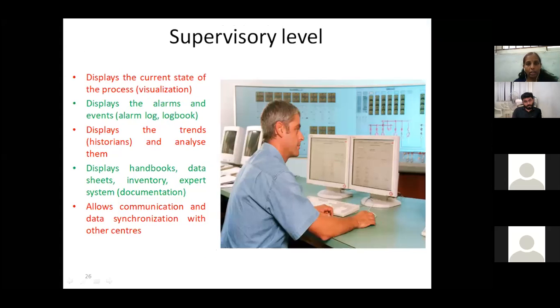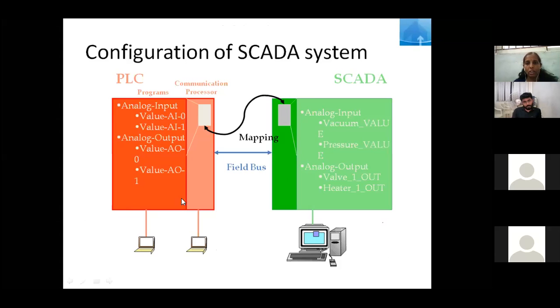So this is how a PLC can be communicated through a SCADA. All the IOs are communicated directly through the field bus. There is a server called the open access server, the OPC data server, through which data can be communicated. A separate software is used for this programming. For example, Allen Bradley and Rockwell Automation give RSLogix or Studio 5000 based programming software.